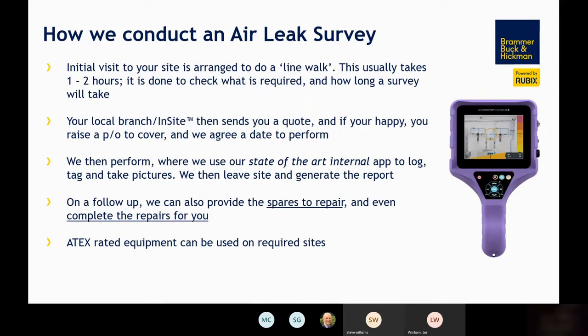So for the typical start to finish routine, we are asked to go to site to discuss an air leak. Once on site, we ask typical but important questions about your compressors and general air systems. We also walk around to scope up the time it will take to perform. We detect leaks with state-of-the-art leak shooters, which visualize the leak and record the amplitude. The image is also used in the report for evidence. We record the details of the leak on our own software, which has been designed around customers' requirements to give you reports that give you relevant and accurate information.